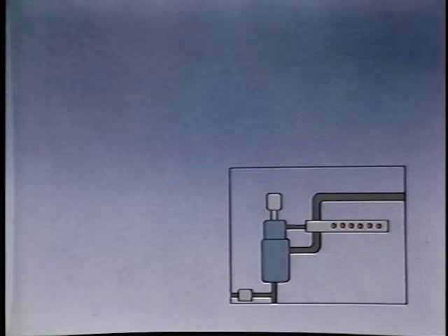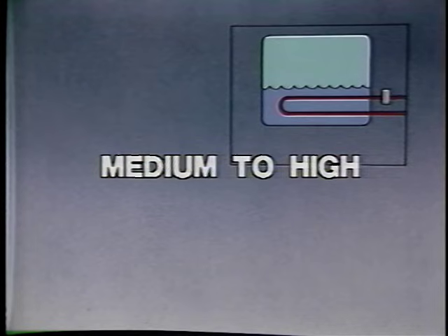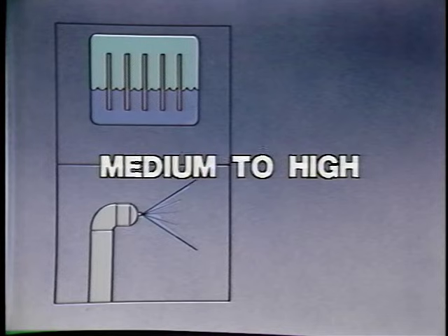As we've said, maintenance on a steam humidifier is negligible, about once a year. Depending on the feed water quality, evaporative pan systems should be inspected or cleaned weekly to monthly. Water spray and wetted element humidifiers may also require weekly cleaning, but need attention at least once a month. When we compile the results, the application range of each method becomes obvious.